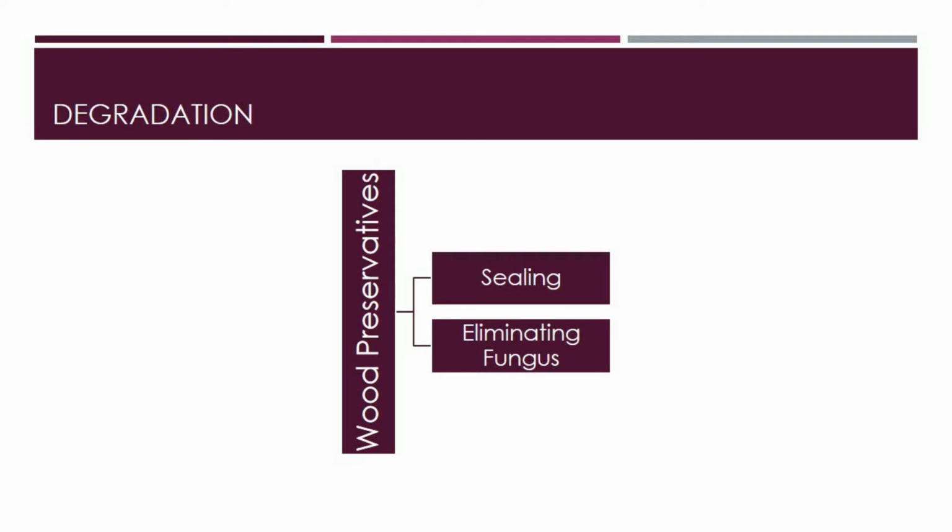The bolt holes in poles can be deformed by a variety of factors. In most cases, such malformations cause no immediate concerns. Deformed holes, on the other hand, can cause the structure to fail as well as other components attached to the pole to fail. Bolts can also loosen, elongate, bend, crack, shear, or break, and become lost.